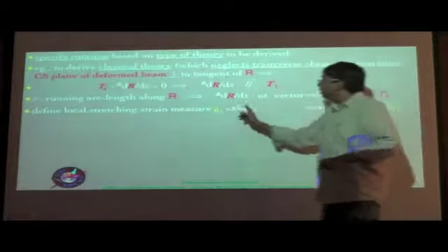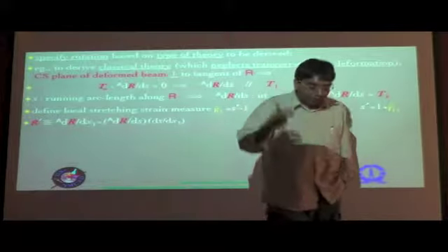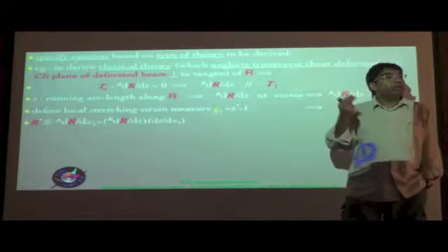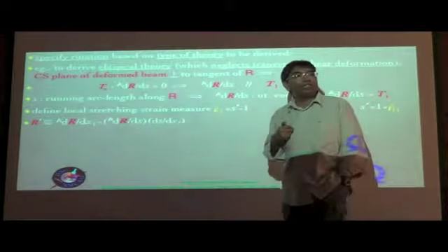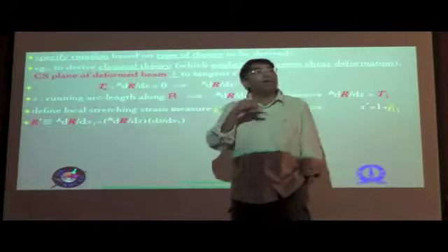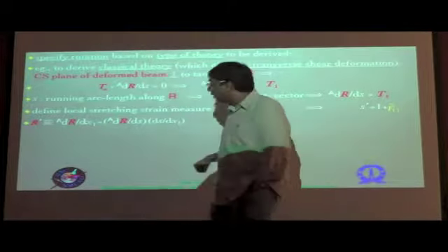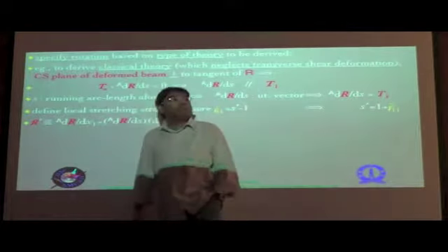So we can just put the 1 on the other side, and therefore you can get an expression for S prime as 1 plus gamma 11 bar, because eventually we want to express this in a particular way. So S prime is equal to 1 plus gamma 11 bar. Now we will need R prime, because we are later on going to determine the 3D strains for which we need the deformation gradient tensors, which in turn means that we need the covariant basis vectors in the deformed configuration, for which we have to take the derivatives of R hat with respect to x1, and that will also involve a derivative of big R with respect to x1. So we need to know what is big R prime.